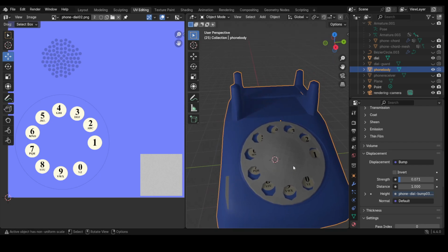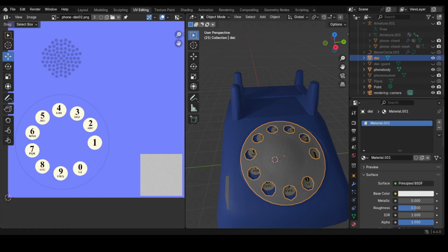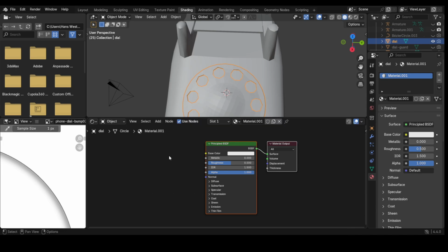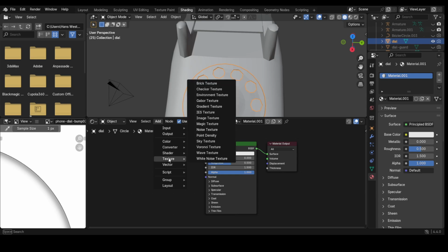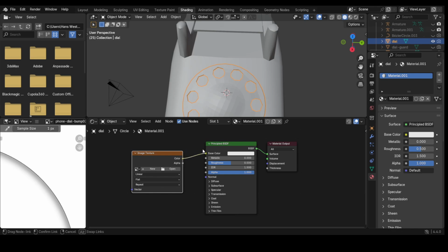And we're going to go and work with the next object, which is this one right here. So let's create a new texture right there. Add a new, back to the shader, and this time I am going to go again also into the first add texture image, bring this over to color, to base color.